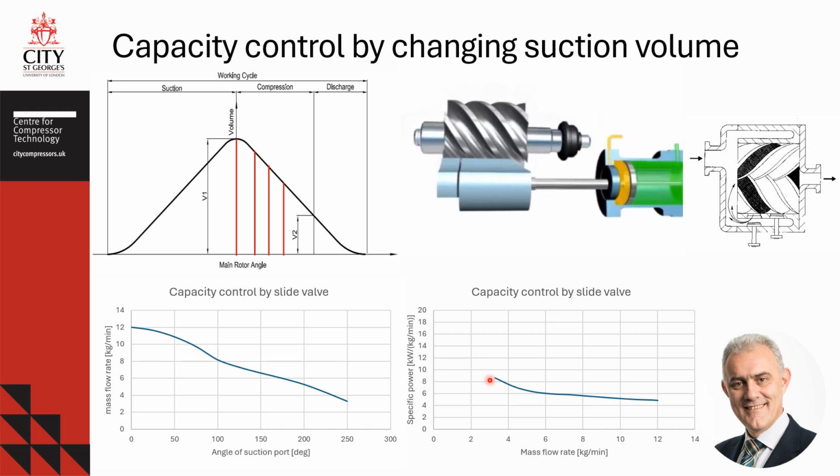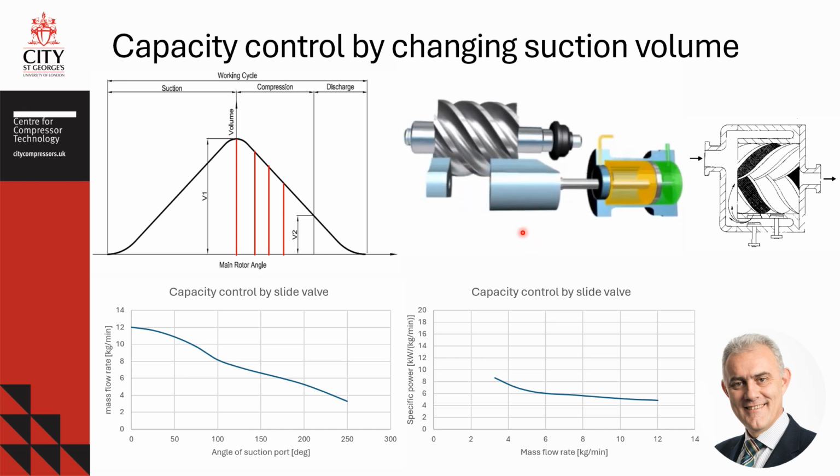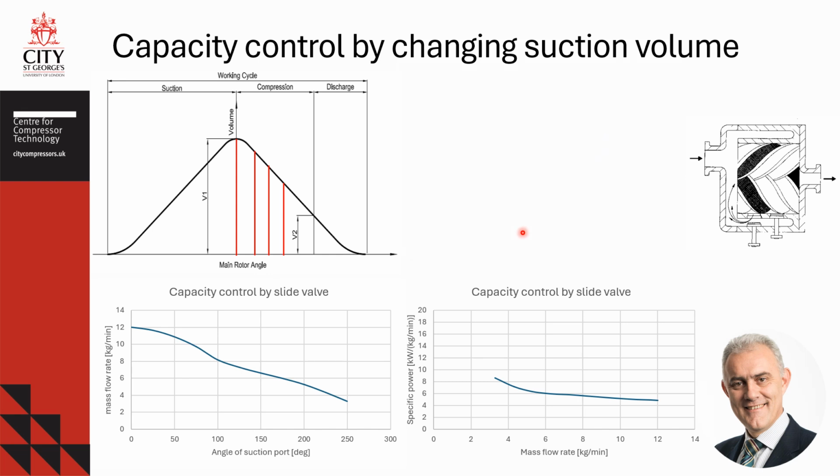Although relatively efficient, a slide valve can significantly increase complexity and cost of a screw compressor, and therefore it is commonly used only for large screw compressors.